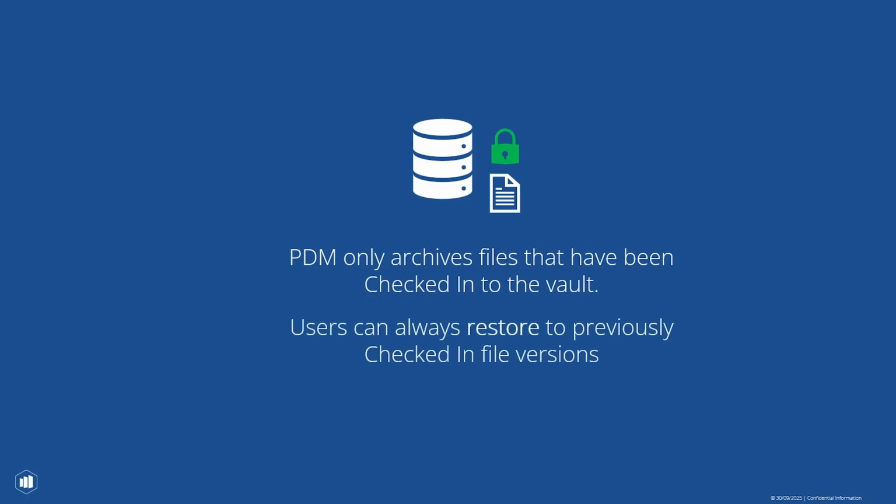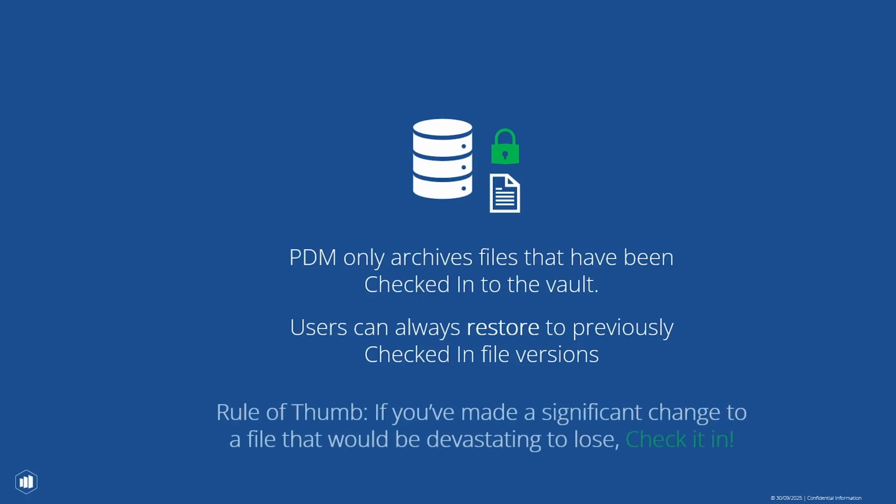Because how this can help you is that users can always restore to previously checked in versions. If the files are checked in every day or so, then if you have some kind of unexpected failure, you're only ever losing a maximum of 1 day's work, right? So generally, a rule of thumb is that if you've made a significant change that would be devastating to lose, make sure you check that in, okay? Maybe it's only been 1 or 2 hours of work, but you solved a really complex modeling challenge in your SOLIDWORKS file, and it would be really difficult to redo that work, okay? So check in early, check in often.